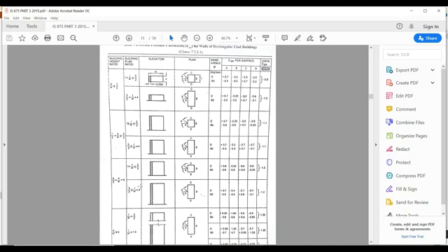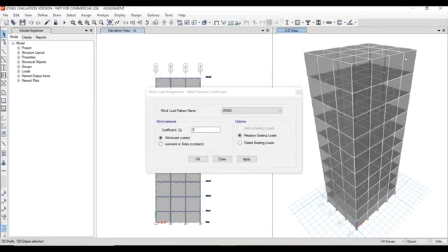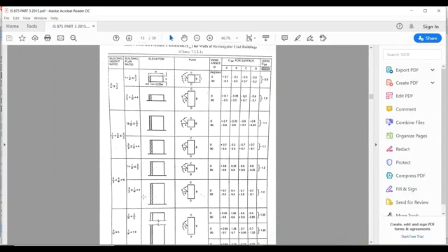And from 3 by 2 to 6, we have the length by width ratio. The length is 4 spans of 4 meters, 16 meters. So 16 meters of length and width of 12. 16 by 12 is 1.33, which is between 1 and 1.5. So from this, at theta equal to 0 degrees, we have a coefficient of plus 0.8 in the A direction and minus 0.25, minus 0.8 and minus 0.8 in the remaining directions.